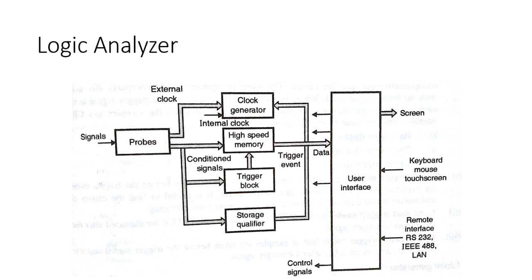Why the logic analyzer is important, let me explain. If you see any digital or embedded circuit, there are different types of digital signals present there, and clock signals are there. At the same time we have to take a number of test points and see the relation between them: whether there is a glitch or not, whether there are timing errors or not, whether the signals are synchronous or not. In that case some type of instrument is required which can accept n number of digital signals at a time and give you a plot on the screen about the timing parameters of those multiple signals.